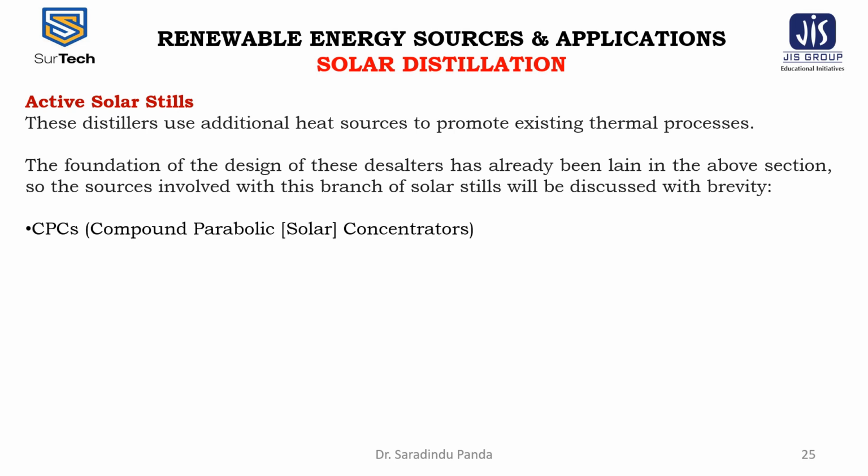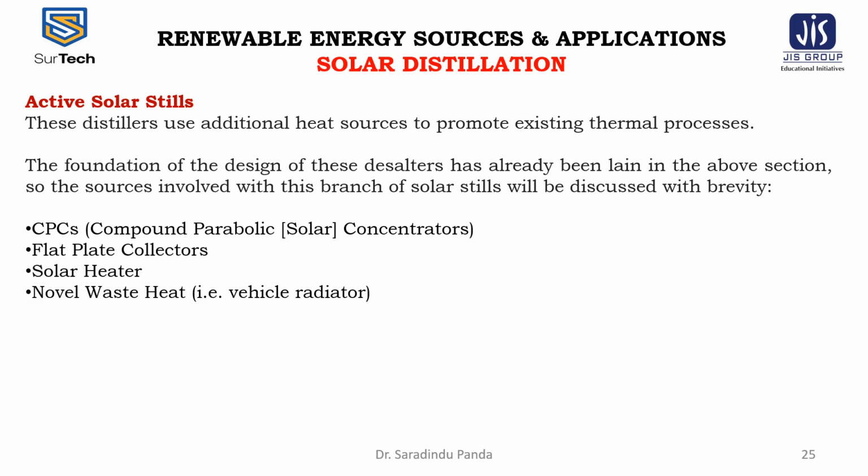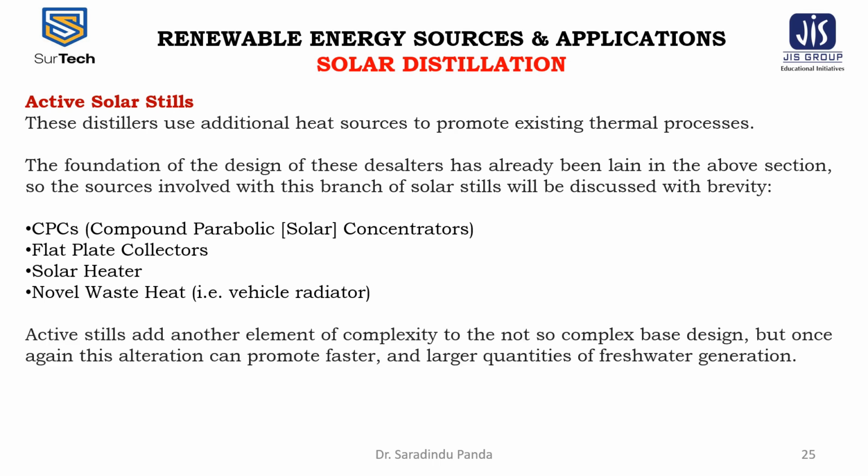The CPC, that is the compound parabolic concentrators, flat plate collectors, solar heater, waste heat, such as the vehicle radiator. The active stills add another element of complexity to the not so complex base design, but once again this alteration can promote faster and larger quantities of freshwater generation.